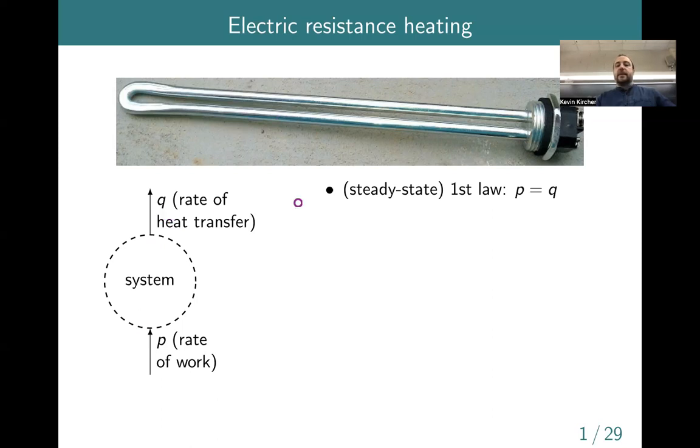So if we look at conservation of energy on that thing, at least as long as it's operating in steady state. If you just begin, say it's at room temperature, and then you let current flow through it, there'll be a warm-up phase where the metal itself, over the course of maybe 30 seconds or a minute, goes from room temperature up to a couple hundred degrees above room temperature, Celsius typically. And then it'll begin to operate in a steady state. It'll stay at about the same temperature, and the electricity going in will roughly equal the heat coming out. So conservation of energy basically says that the electrical power going in is equal to the thermal power.